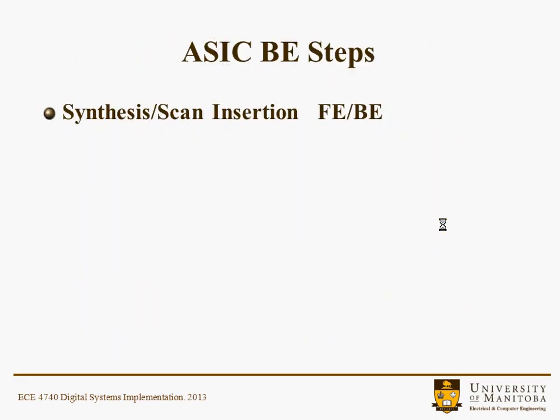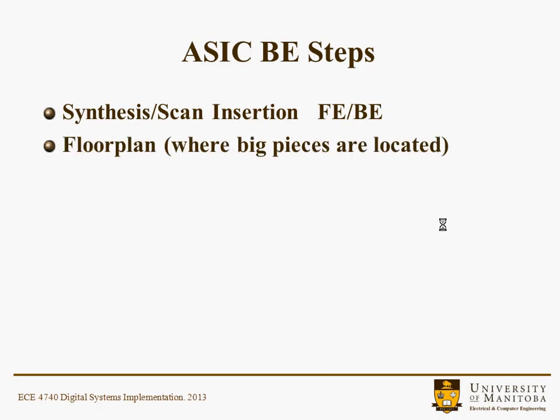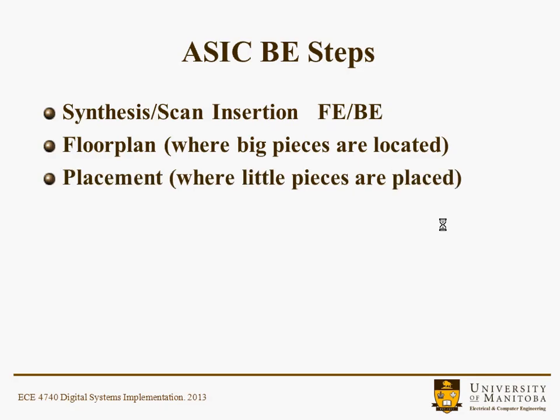Some of the back-end steps are synthesis and scan insertion. It's sort of somewhere between front end and back end. Clearly the synthesis part is taking your HDL to a netlist, and that is a part of the synthesis step. The reason it's listed here as back end is because it has some automatic scan insertion. What scan insertion allows you to do is implement some test fixtures that you don't explicitly design for but get added for you. The floor plan stage is sort of where the big pieces of the chip are located, and the placement is typically where the little pieces are placed and routed,